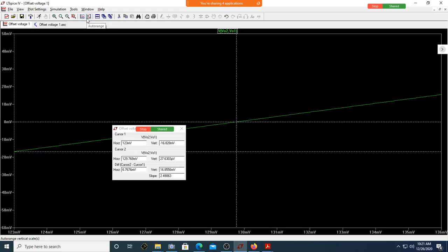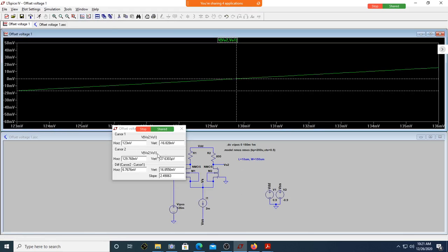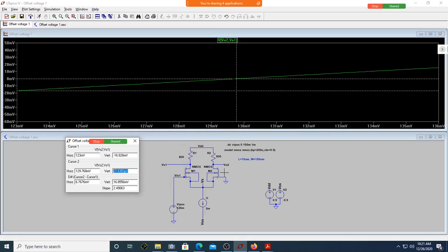Now, of course, we are able to exactly zero down the output offset voltage by sweeping the input voltage, because if you vary this, the output offset voltage is going to change. That's how the output offset voltage will become 0 when you apply an appropriate polarity input offset voltage of a certain magnitude. Okay, so on this line you may have to do it for the other two combinations.